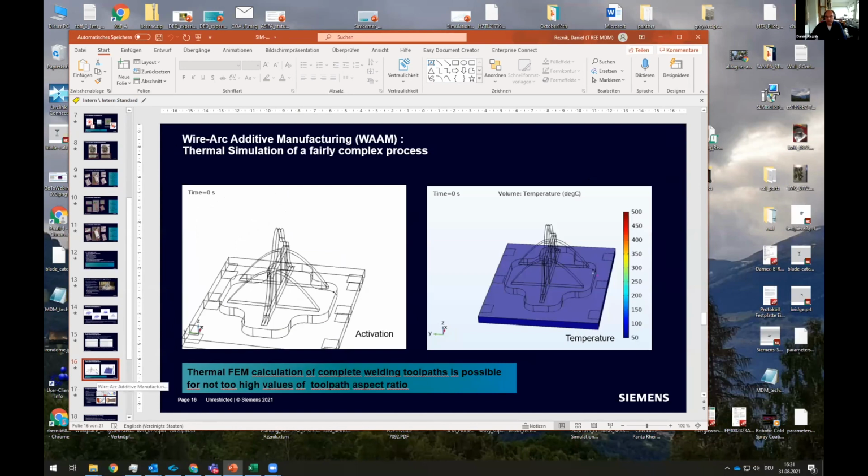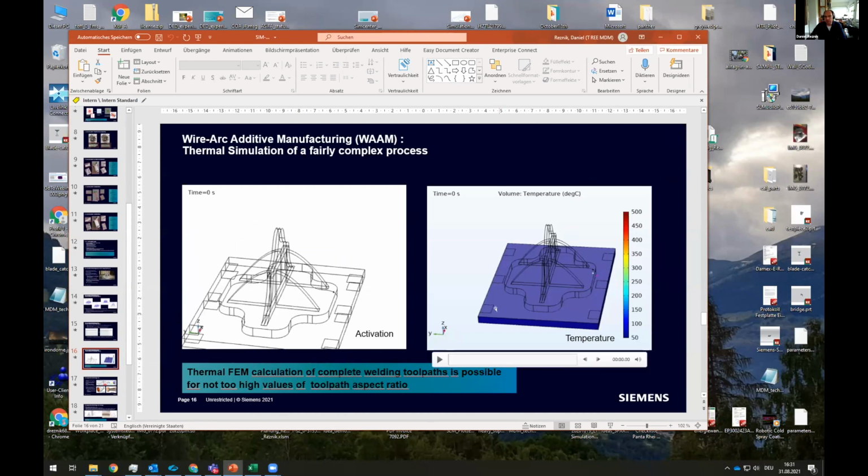Maybe I didn't express it very well. Actually the goal here is to keep track that the temperature of the area you weld to should not be too high, because then you get degradation of the material. So it's like keeping the overall thermal budget correct. If you raise the temperature above some value, then you get problems with oxidation, for example. Okay, thank you very much.